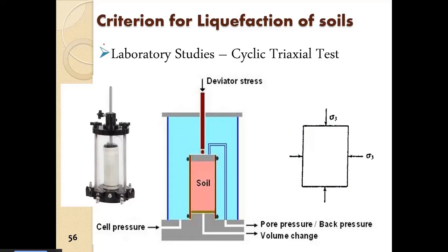during liquefaction. So to study that in detail, we take help of laboratory studies, obviously the triaxial test, as we have seen in our classes where we discussed the various advantages of the triaxial test. So in liquefaction study, mainly we have three types of triaxial test. One is UU, one is CU, and one is CD.